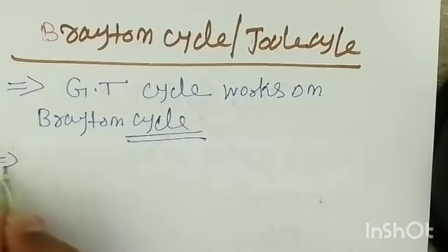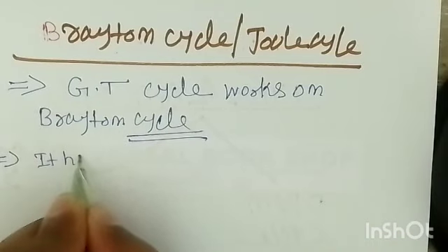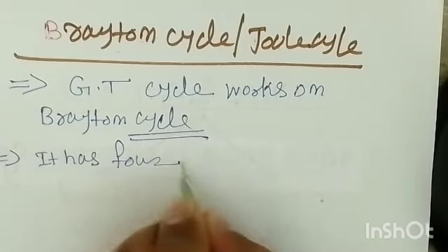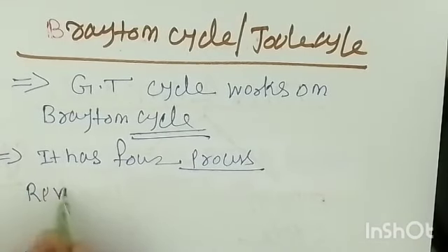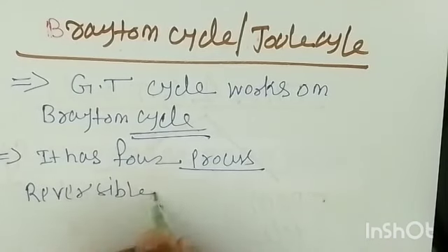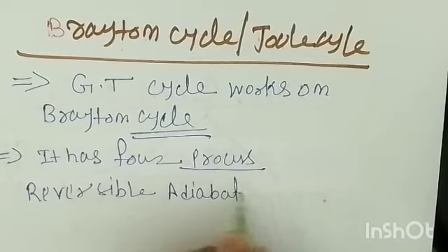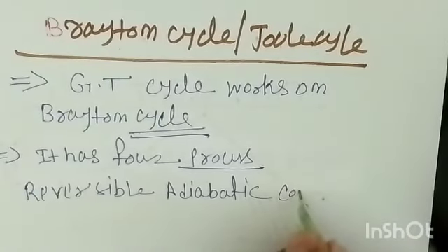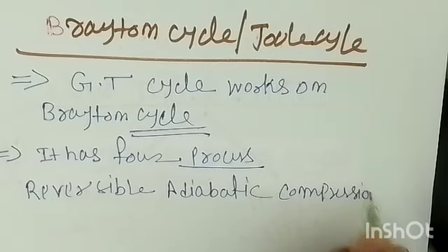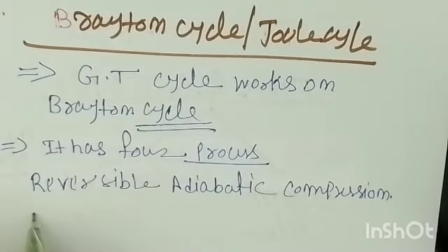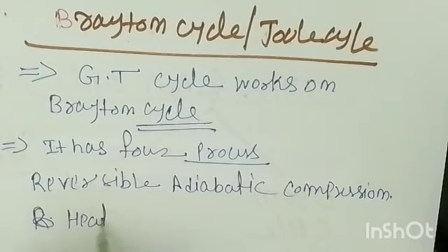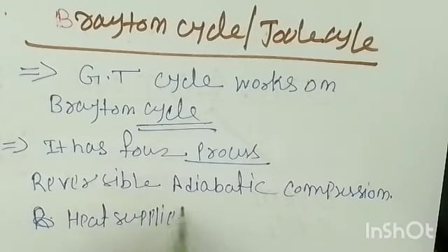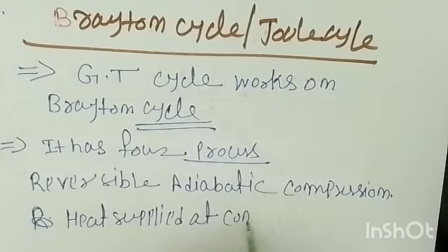So you can say that it has 4 processes, right? And what are those? First, the reversible adiabatic compression. Second one is reversible, after compression you have to add the heat, means heat supplied at constant pressure, right?